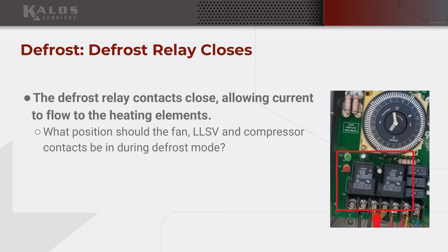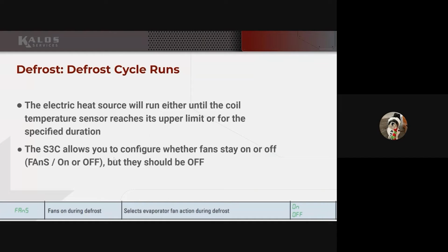So, okay, I'm going to just ask the question, look for a response. Just somebody, don't be shy. What position should the fan, liquid line solenoid, and compressor be? What position should those contacts be during defrost mode, open or closed? Open.